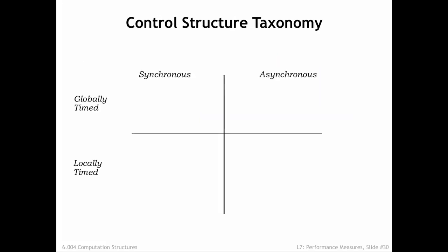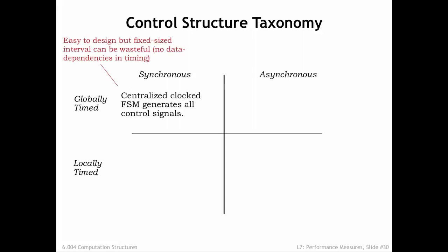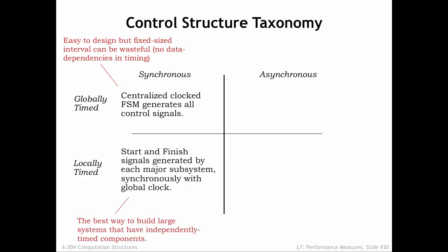Let's summarize what we've learned about controlling pipeline systems. The most straightforward approach is to use a pipeline with a system clock chosen to accommodate the worst-case processing time. These systems are easy to design, but can't produce higher throughputs if the processing stages might run more quickly for some data values. We saw that we could use a simple handshake protocol to move data through the system. All communication still happens on the rising edge of the system clock, but the specific clock edge used to transfer data is determined by the stages themselves.